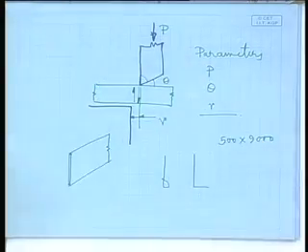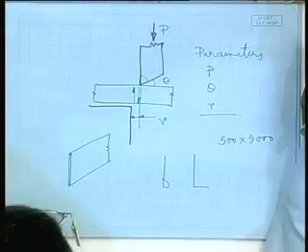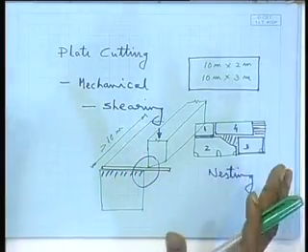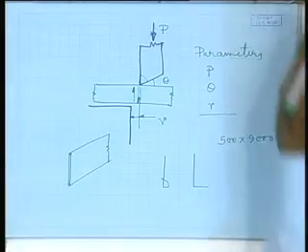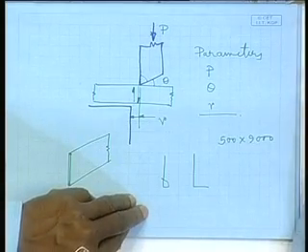That is how. So, these shearing machines, I mean mechanical cutting, though it has limitations, we will still find their usage in shipyards, because there is a requirement for flats, straight edges which need to be cut. So, they are preferable to cut in the shearing machines. You will have fixtures such that with the help of a crane you put the plate on the cutting bed, adjust it, and with a stroke you get it cut. So, that is how mechanical cutting is quite a convenient, easy and fast method, but the only disadvantage is that it can cut only straight edges, not curved or any other shapes. So, it is limited to that.